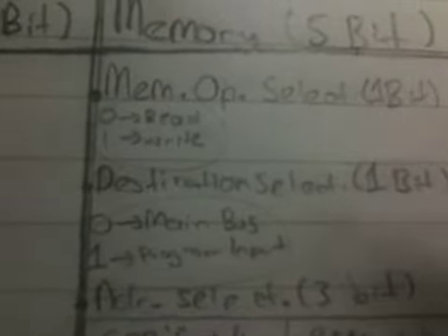And if we didn't give any branch commands, then it's just a value that you can write into either these general purpose registers or RAM, and you select it from here. Main bus is like where data flows, and you can just pull data from that bus and save it to GPR or RAM. But the program input, which is this 8-bit value here, you can save to any of these GPRs or RAM. So it's pretty awesome.